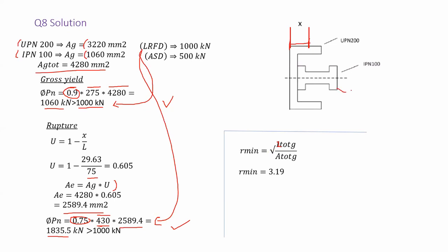For example, for this one, you calculate the moment of inertia. Let's say that this is your x-axis and that one is your y-axis. At the beginning, you find for this section, call it I1, the moment of inertia. You find it in the x direction and in the y direction. Call them I1x and I1y. And then for the UPN, you check the moment of inertia about the x-axis and the y-axis. You can call them I2x and I2y.